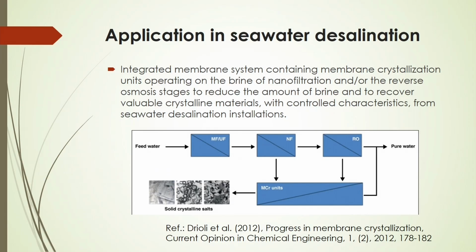Now, you can use this for application in seawater desalination. In this case, an integrated membrane system containing membrane crystallization units operating on the brine of nanofiltration and or reverse osmosis stages can reduce the amount of brine and recover valuable crystalline materials with controlled characteristics from seawater desalination installations, according to Gioli et al.